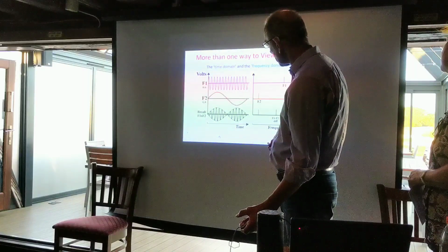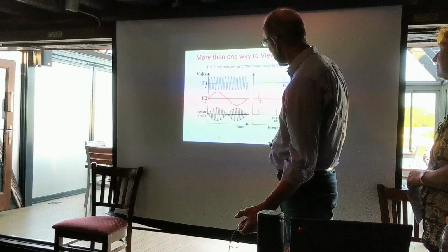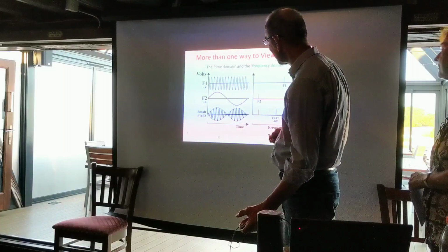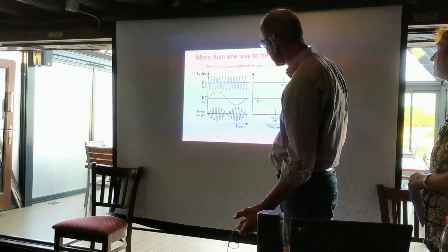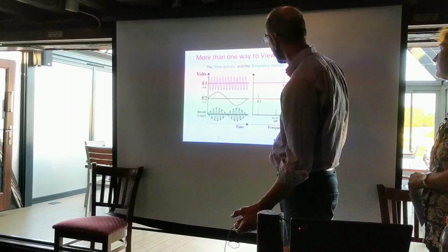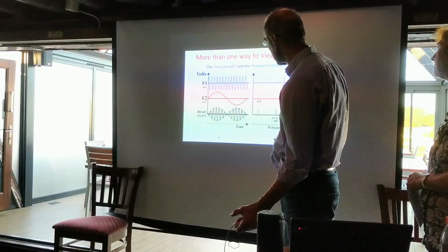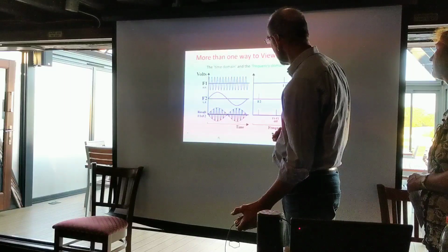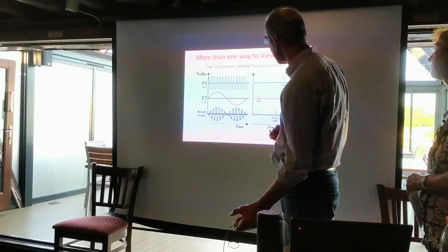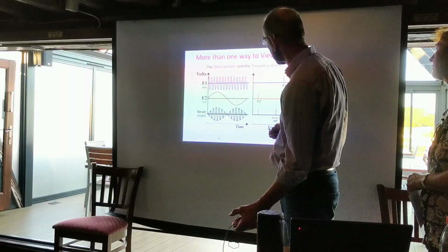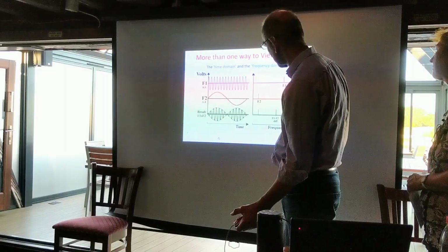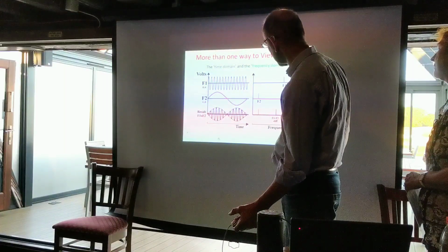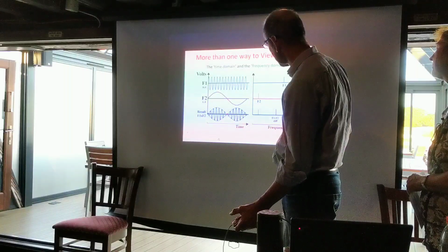If we were to multiply f1 by f2, then you can see f2 is 0 here, and anything multiplied by 0 will be 0, so the result is 0. Here, f2 is at its highest point, we'll call it plus 1, so the sine wave at that point will be multiplied by the biggest value of this, and you can see that reflected in the trace here. At this point we go back to 0, we're multiplying by 0, so we get nothing out.